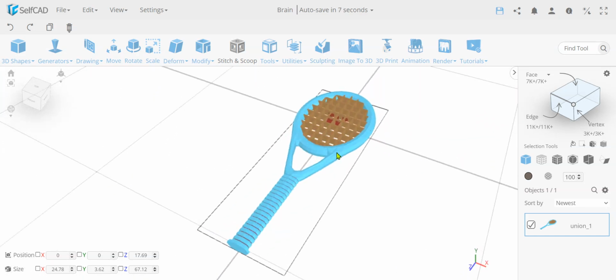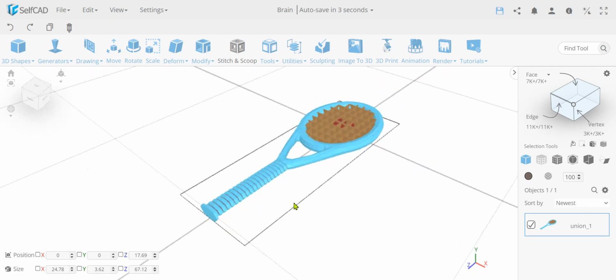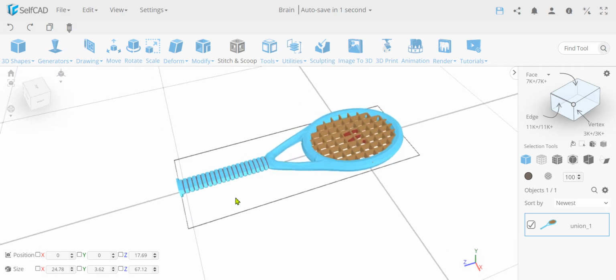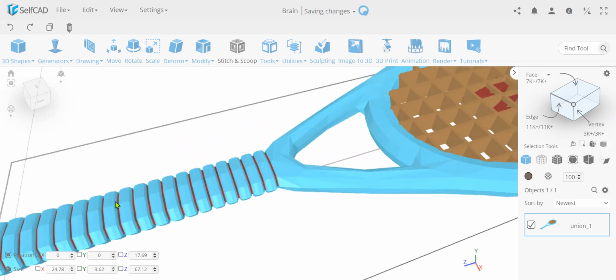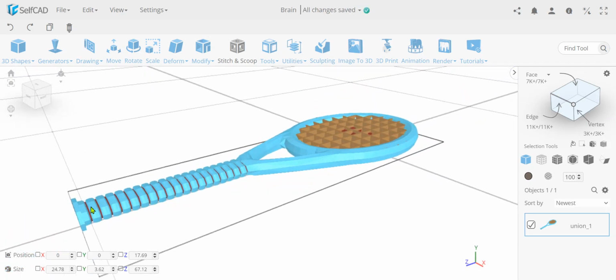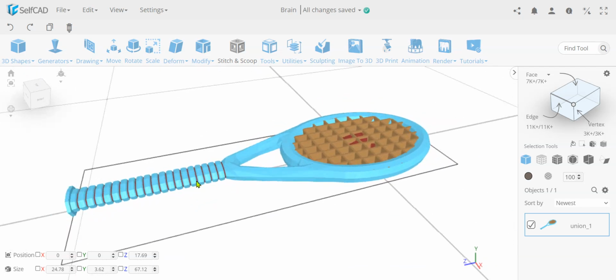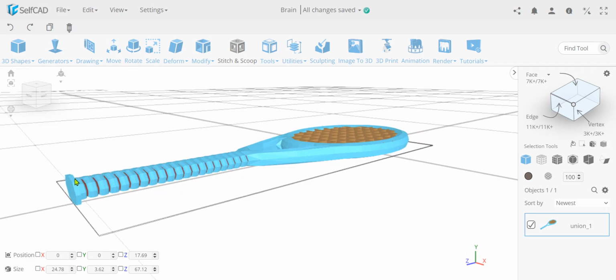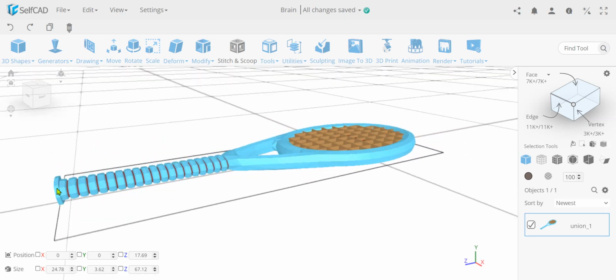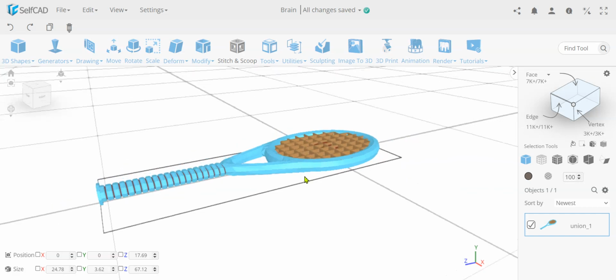Later I used this extrusion, actually inset and move, and then I bridged this section. Here I extruded with a custom pattern extrusion to give me the different things, and then I selected the custom pattern and extruded to make the engravings and colored them. Then we extruded this side and then added the face to push it out.